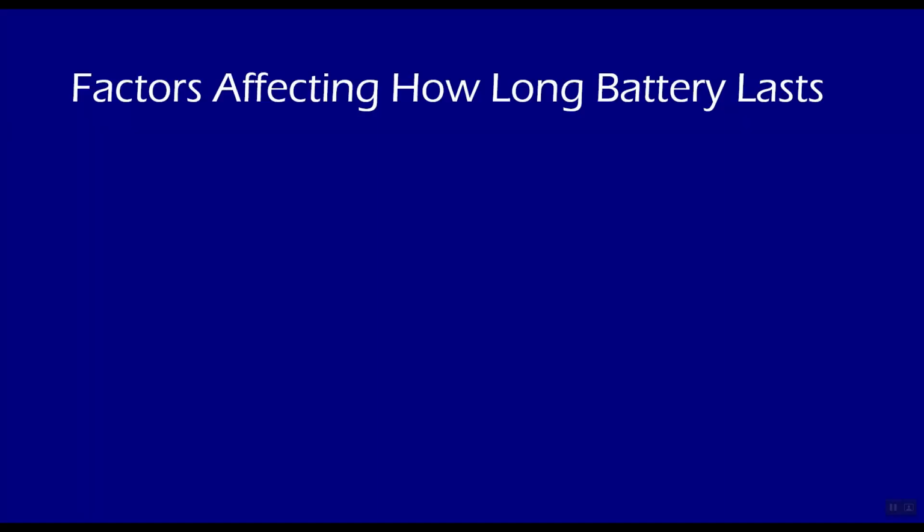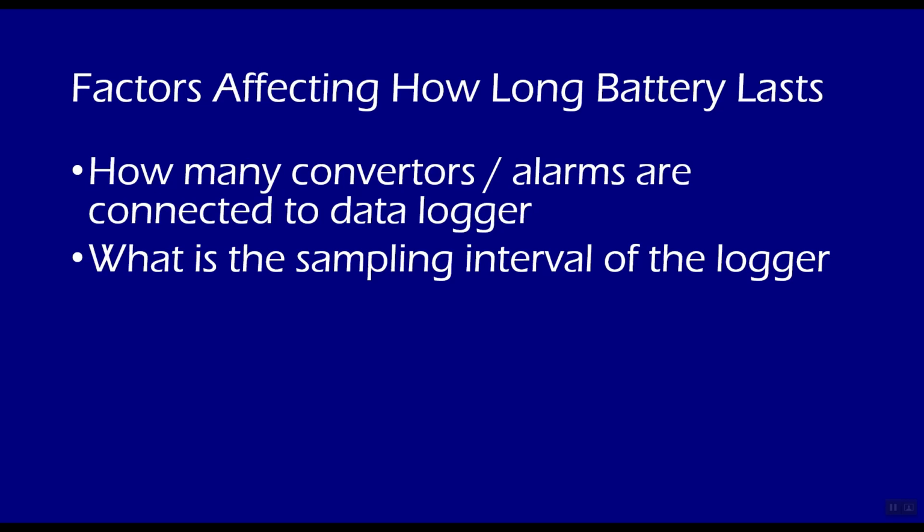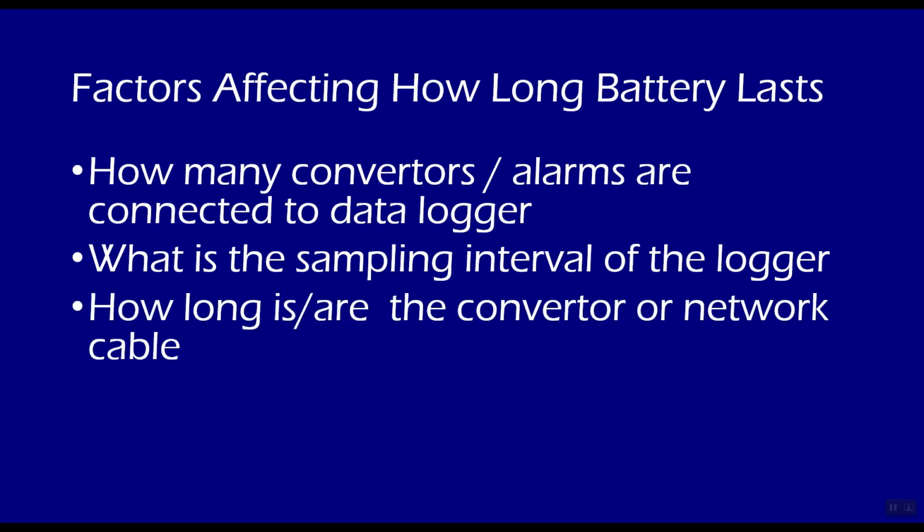Now this begs the question, how long will the data logger last on a battery backup? Well, this depends on a number of factors. How many converters are connected to your logger, as these are powered by the data logger from the converter cable. Obviously the more converters you have, the more current it will consume. What sampling interval are you using? For example, sampling at 1 minute intervals will use more battery than say every 30 minutes. How long are your converter cables that connect your converters and or alarms? Are you using the standard 5 meter converter cable that came supplied with your units, or have you made a 200 meter long cable?